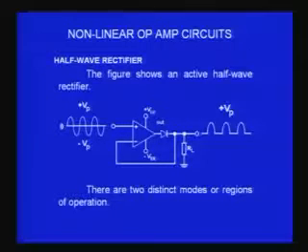Even if the input voltage is just around 100 microvolts, I multiply by 10 power 5, and so you get about 1 volt at this point. So, you get 1 volt, which means the diode will be forward biased, because at the output of the amplifier it is about 1 volt, and at the other side it is close to ground.